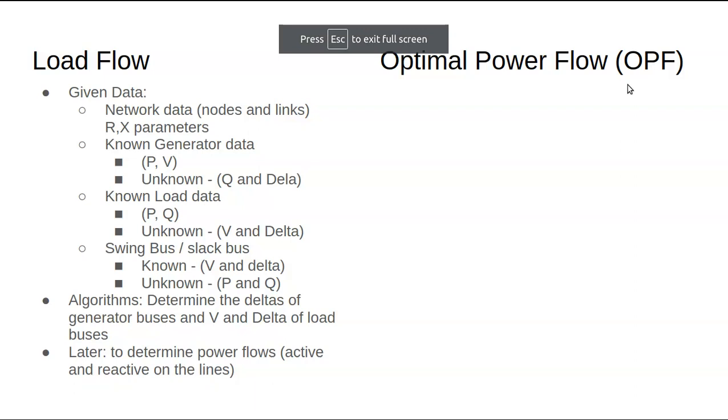But in a network and a set of conditions, the balance of that megawatt MVAR may not be balanced. For that, we will consider the PQ unknown for the assumed bus, and practically all voltages are with respect to ground. So for mathematical implementation, we will put one generator as a swing bus, for balancing load and generation. Basically, what he is answering is that a swing bus is needed to balance the P.